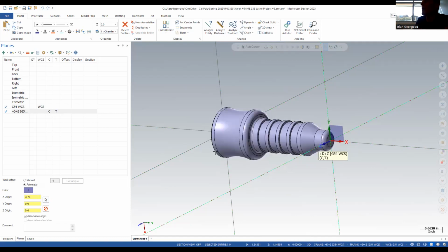So that's the other way to do it. I'd probably just do it the D positive, Z positive way, right? Now the second, that was easy too. You pick. But what you need basically is a coordinate system set up for the lathe with the Z and the X, or the Z and the D. Yes.